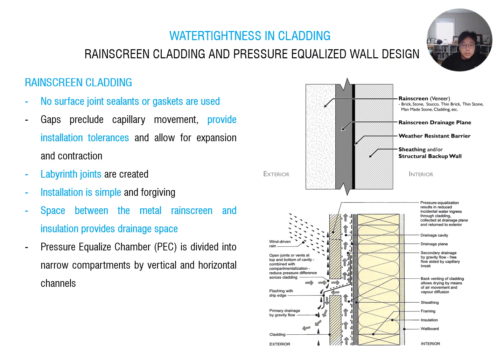So this is also when we talk about the rain screen system, rain screen cladding. You have to remember one thing. We already talked about the rain screen assembly a lot: gypsum board, the framing, insulation, fiberglass mesh sheeting, rigid insulation outside, and waterproof membrane. And we have to provide this open cavity space, but the rain screen system has to provide a 1 inch to 2 inch gap, because we have to provide enough space for ventilating the air to dry out the water.